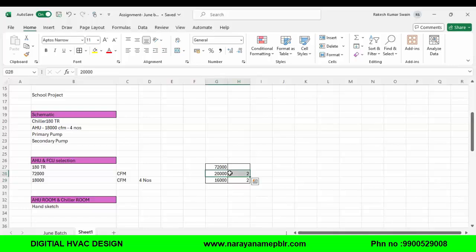What about FCU, the fan coil unit? Both are the same actually, AHU and FCU. If your capacity is more, then it is AHU. If capacity is less, it is FCU. Inside, in VRF we have used cassette units, and in some places we have used ducted units. Those things you can also select as per the requirement. Already we have done selection for FCU in VRF.